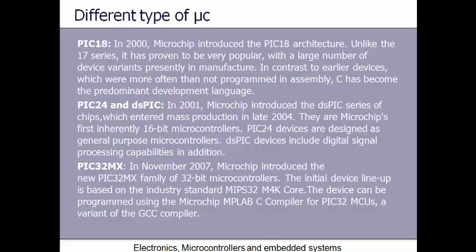For example, there is a difference between the one we'll see today, the 16F84, which has two ports, one with 5 and one with 8 input output pins, and the next microcontroller we will be seeing in the future, the 16F877, which has 3 ports.